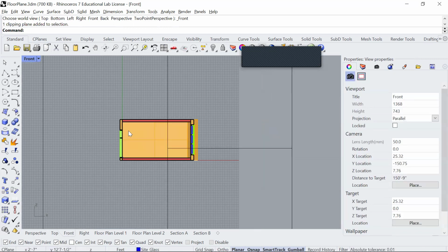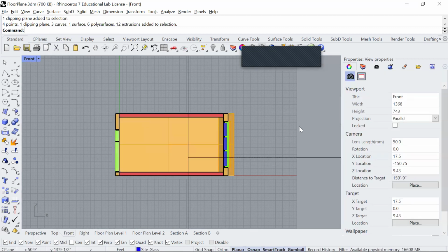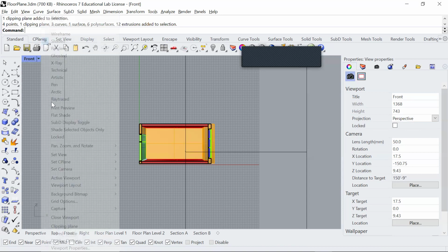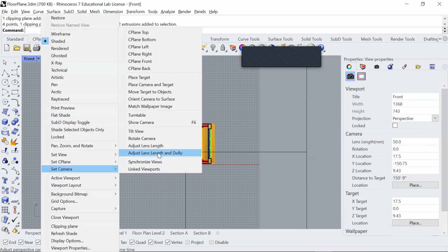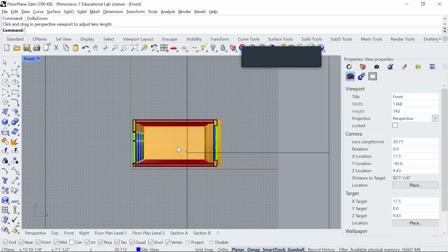Now, if I do a make 2D of this, it will be the same as the plan, so you have things projected, but you won't have the perspective. So we do not select anything and we change, on the properties panel, the projection to be perspective. You can emphasize the camera lens to make it a little more effective.